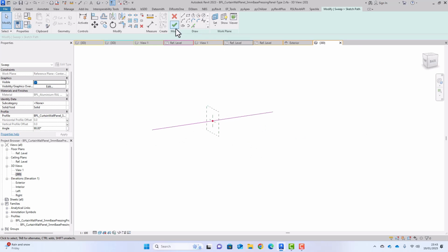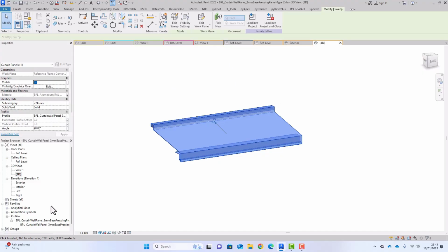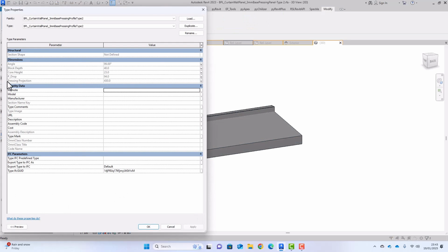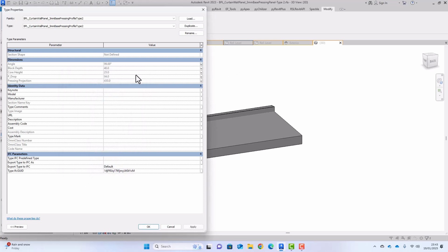If you create a line, you constrain the line, and then you add your profile. And you can see just the profile that we created. Once you've got that, you can press finish. Anytime you bring your profile, in order for you to bring all the parameters created in the profile, you take the properties tab on the profile, and every parameter that we've done within the profile family, we can import it into this family.